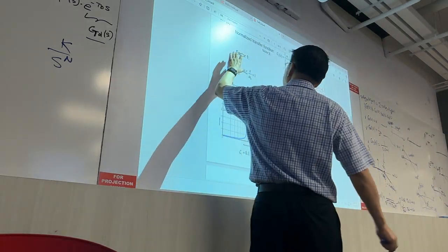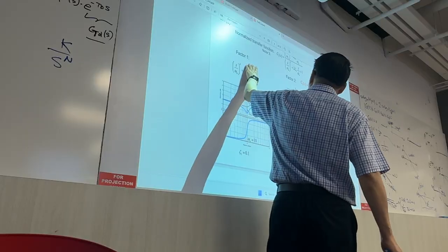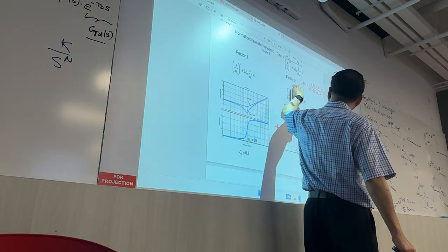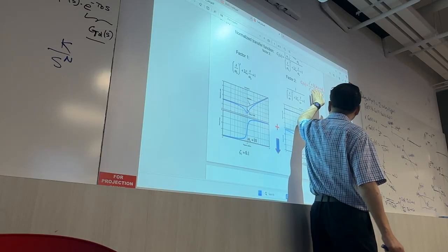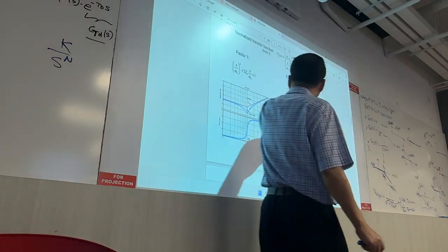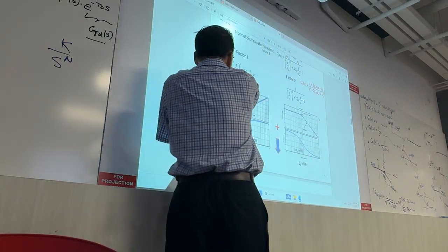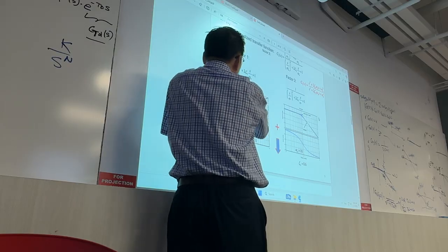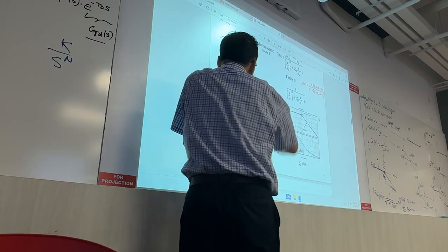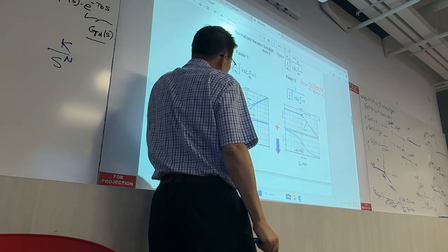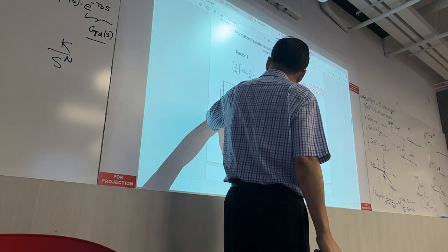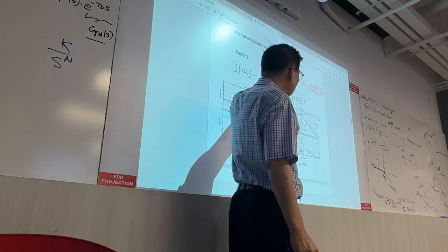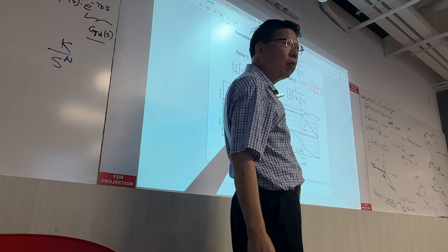If you draw this factor 1 in the numerator and then factor 2 in the denominator, so you separate this as a G1 here, this is G2. You can have 2 basic factors. This guy gives you this in the numerator, and then it has a corner frequency of omega, and then this is going up at the rate of 40 dB per decade.